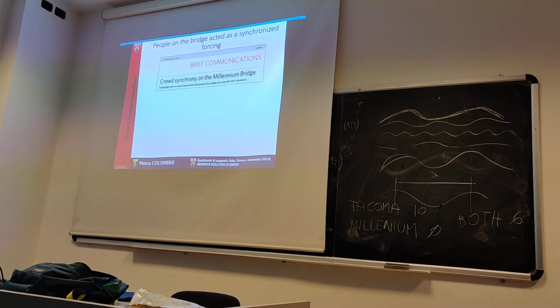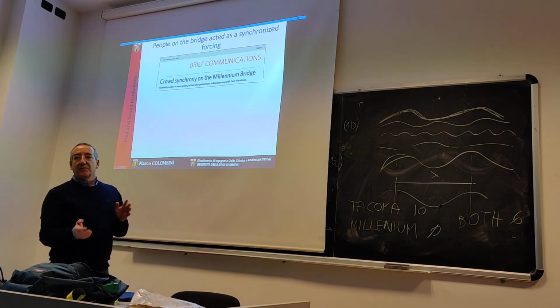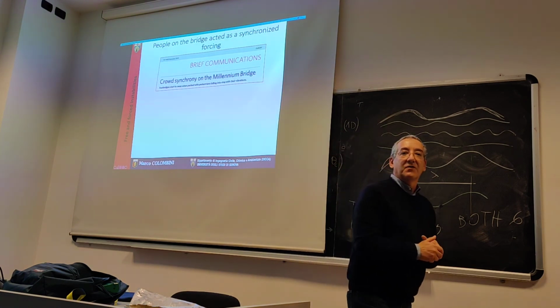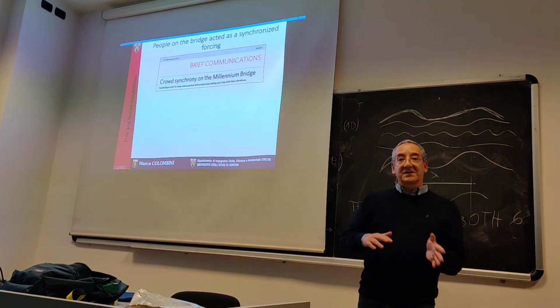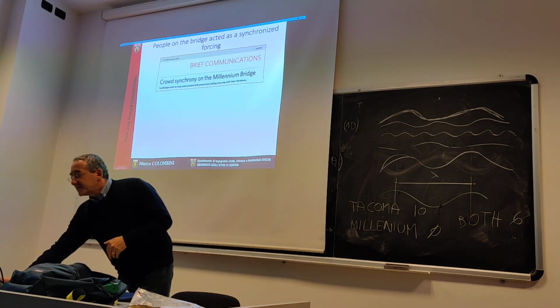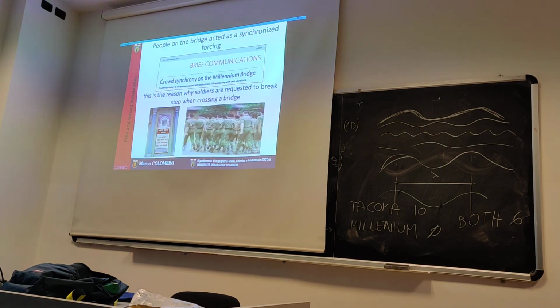This is a paper in Nature in 2005, which says footbridges start to sway when packed with pedestrians falling into step with their vibrations. So they synchronize. If you are walking on a bridge and the bridge starts to oscillate, you tend to move your feet in time with the forcing, and so you force exactly that frequency, and it tends to amplify and to resonate. This is the reason why soldiers have to break step when they are crossing a bridge. They are specifically requested.